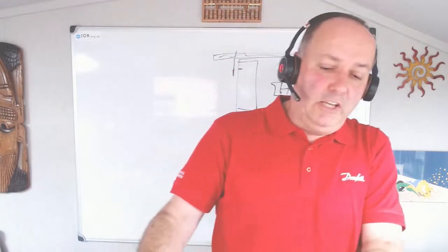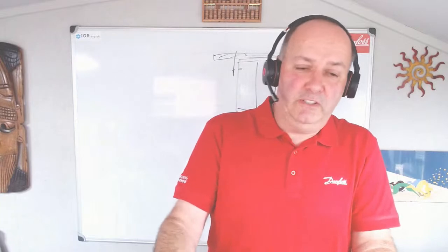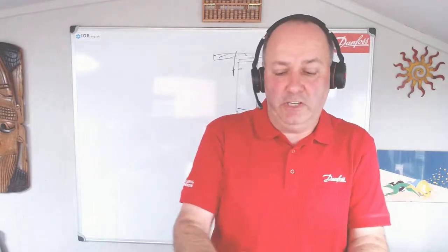Is there any defrost start type sensor? I guess this again comes back to this defrost on demand system that we've got built into the Danfoss controllers in the Adapcool range. In the olden days, when I was on site, I preferred to call it defrost skip, because you'd still have your planned defrosts, maybe 4 a day, and if it thought it could get away with not doing a defrost, it would skip the defrost.